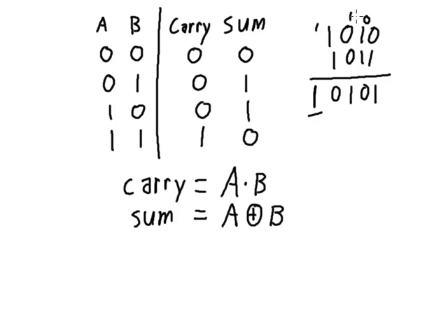And in order to make that circuit, we're going to have to include the carry in as well. Okay, so I'm going to clear my table here, and if I'm including a carry in, that means I've got 3 inputs to my truth table. I'm going to have A, I'm going to have B, and I'm going to have my carry in. I'm just going to call it C in. And then my outputs, I'm going to have the same 2 outputs.